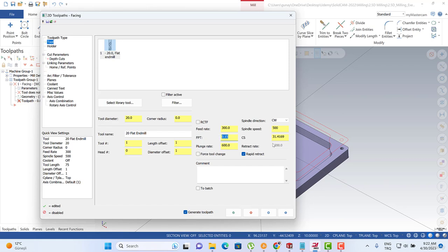0.15 millimeter. And then I just need to write my cutting speed, and the spindle speed and the feed rate are calculated automatically according to these parameters. How can we get those parameters? Actually, this is coming from our tool catalogs.